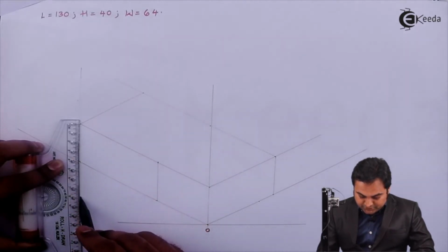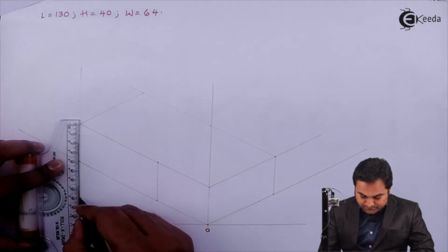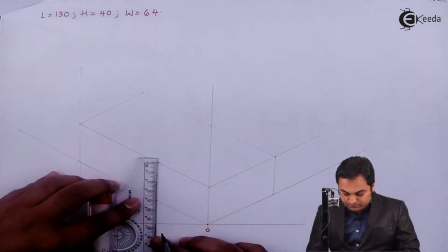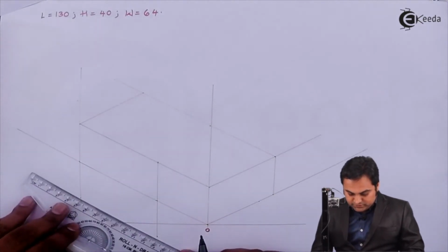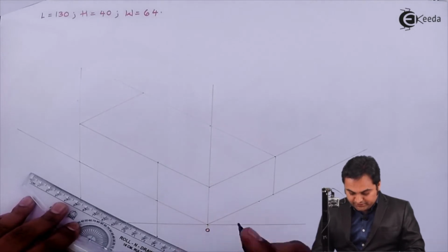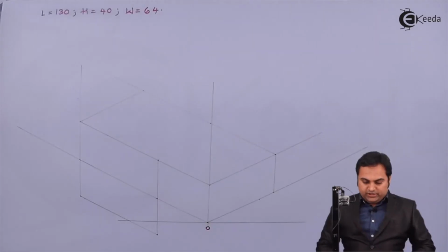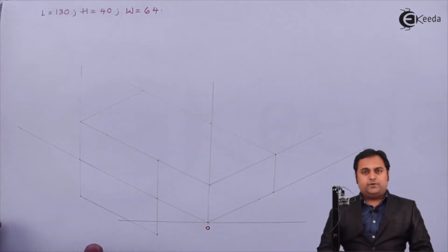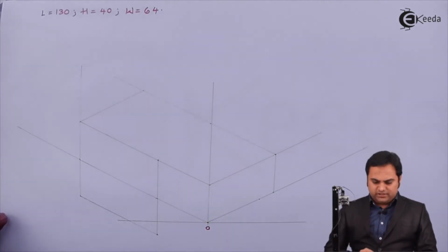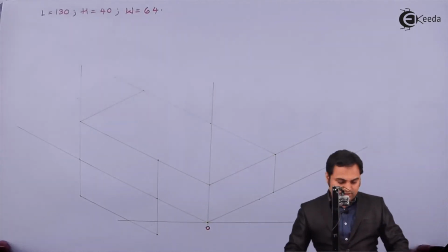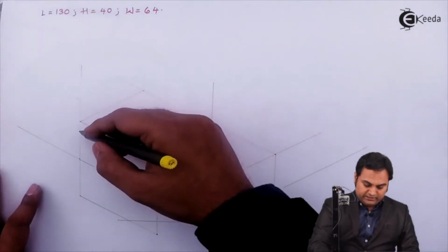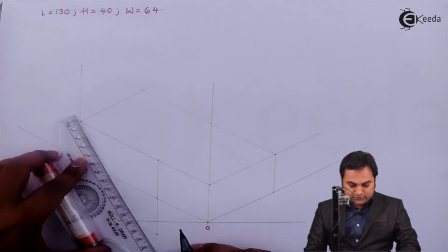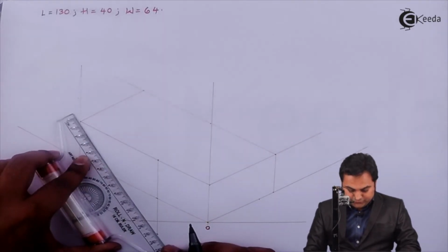Now projecting this vertically down, here I get a point, projecting it down. So this is the parallelogram which is required in the drawing. So here I have drawn the parallelogram which is corresponding to the diameter of the semicircle, which is 80 mm. And next, the procedure is in this parallelogram I should draw a longer diagonal in this way, connecting these 2 points will give me the longer diagonal.